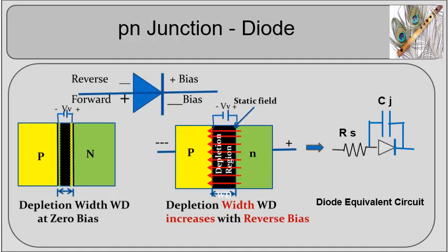Two differently doped P and N materials, when brought into contact, create a P-N junction. Free carriers from either side migrate to the opposite side, recombine and create a charge-free depletion region. The accumulated charges on either side form an internal potential barrier and stop further migration. A depletion layer sandwiched between two conductive layers forms a parasitic capacitor. The silicon bar resistivity creates parasitic resistance.